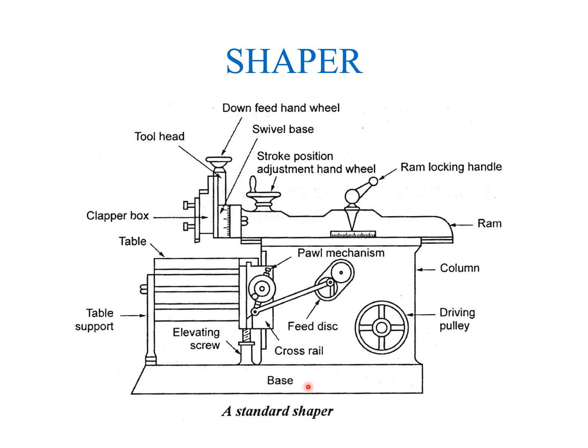Then ram. So this is the ram. It is the main part of the shaper machine. It holds the tool and provides the reciprocating motion to it. It is made of cast iron and moves over ways on the column. It is attached to a rocker arm, which provides its motion in a crank driven machine, and if the machine is hydraulic driven, it is attached to a hydraulic housing.